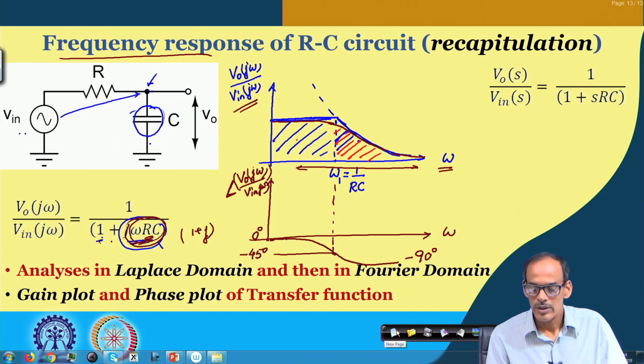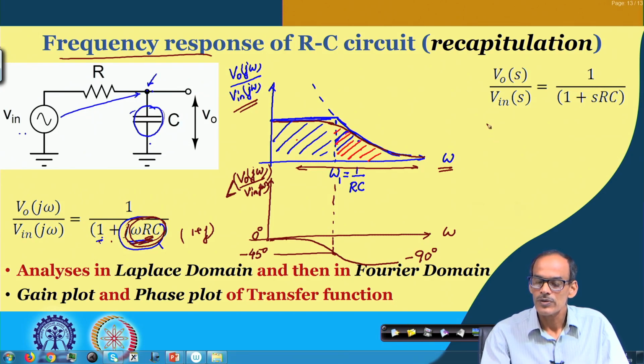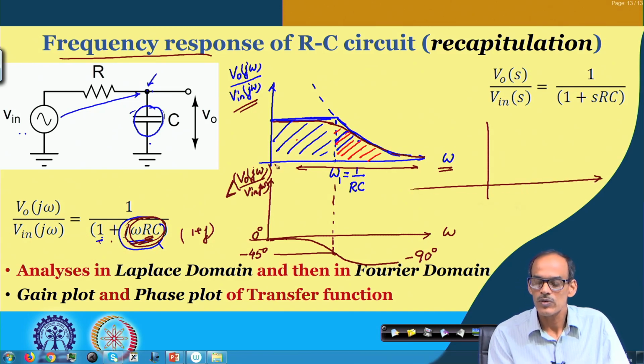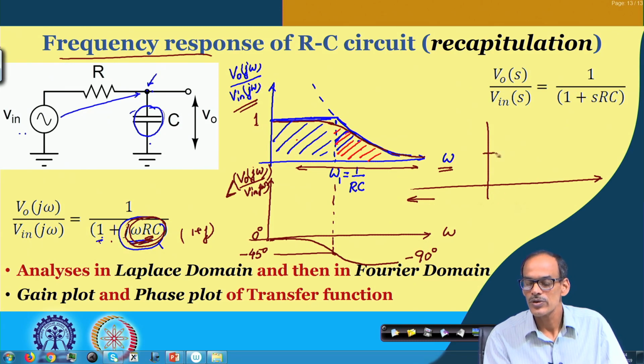So, here again in the Bode plot, similar to the previous case, if you consider omega in log scale, then of course 0 frequency will be pushed to infinite distance, and this one part will be coinciding with 0 dB. Then this hyperbolic part, on the other hand, will have a linear behavior, and at the corner frequency the roll off will start.